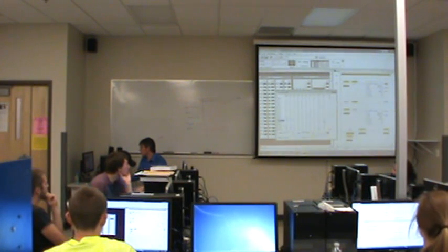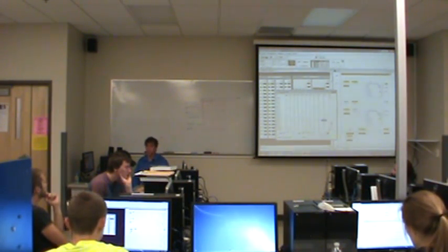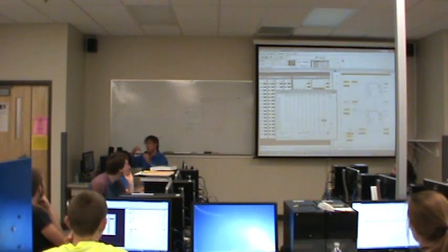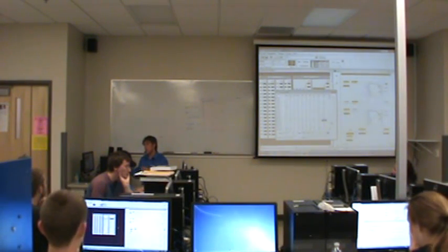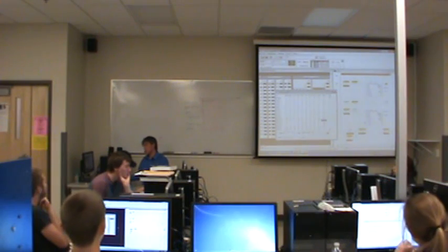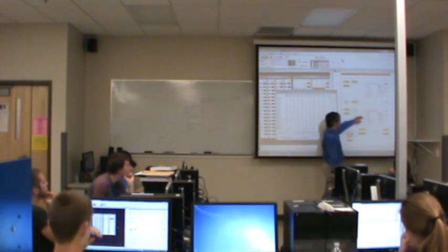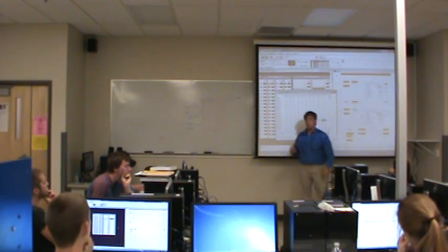If I were to manually write the position word here as 1 instead of 2, it would go backwards. But you have to be tricky because you'd have to write a 0 in there, have it increment so that it actually goes to position 1. Because just writing its current position there won't cause it to change the output. The low to high transition on the run before the instruction. Okay? It's the low to high transition right here that causes it to actually go and set the outputs. So it would be tricky and messy.